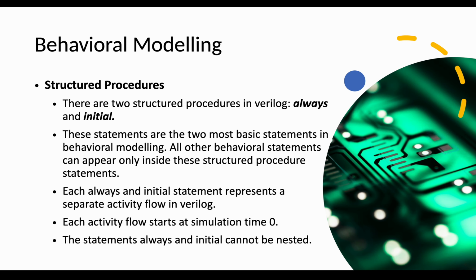Each always and initial statement represents a separate activity flow in Verilog. Each activity flow starts at simulation time 0. The statements always and initial cannot be nested. That's an important point, you have to remember that.